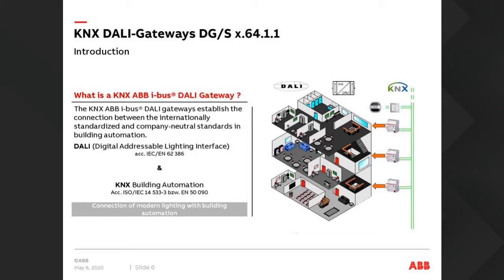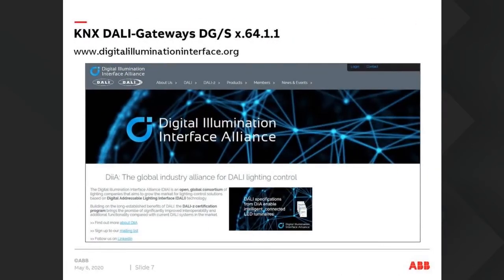Typically, when this is run around and wired by the electrical installer, they'll use a 5-core cable. You'll have 3 cores for live, neutral and earth, or active, neutral and earth, and you will have 2 cores for the DALI plus and DALI minus. So that's typically what you see in most projects, and that's typically the way it's running around the place.